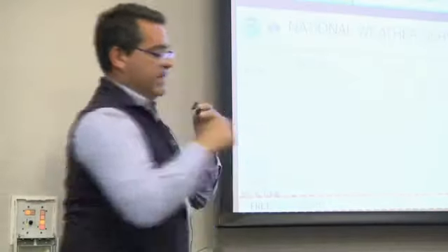You can see here the forecast ET for the following 7 days of the week, and this is very useful for growers as long as they have a sense of the crop coefficient. Anyway, it's another source of information. So the critical part for scheduling irrigation with ET-based scheduling is really having a good crop coefficient value.